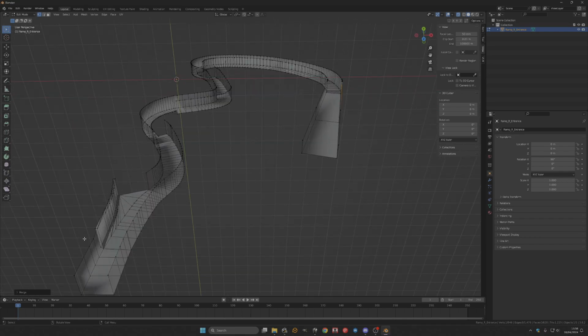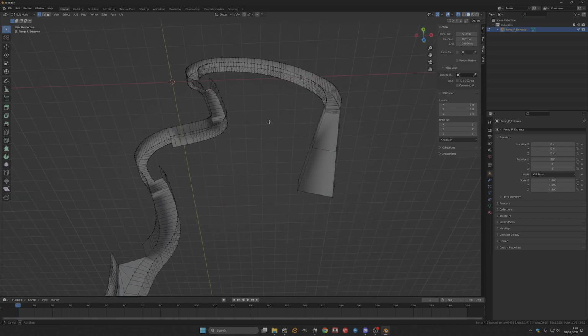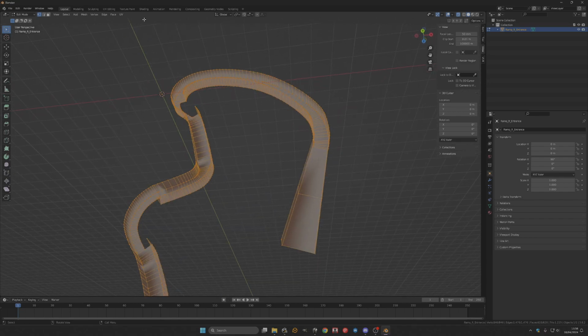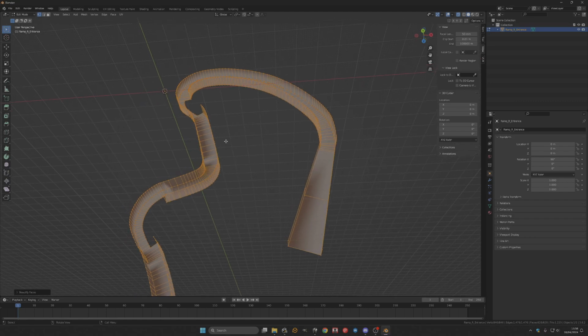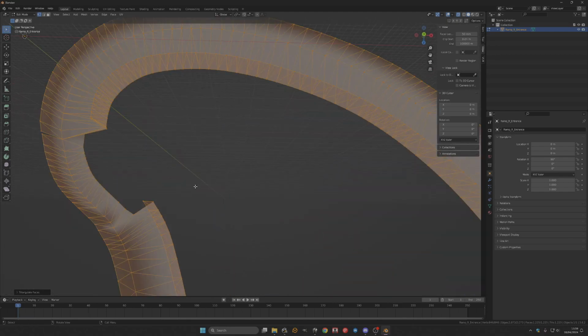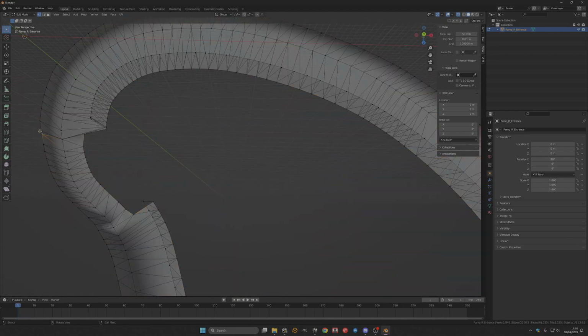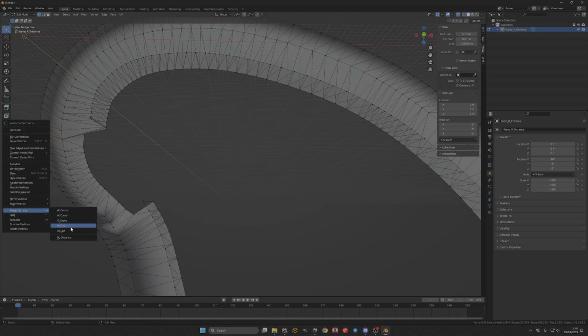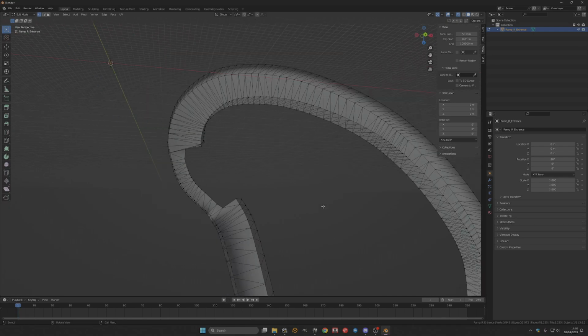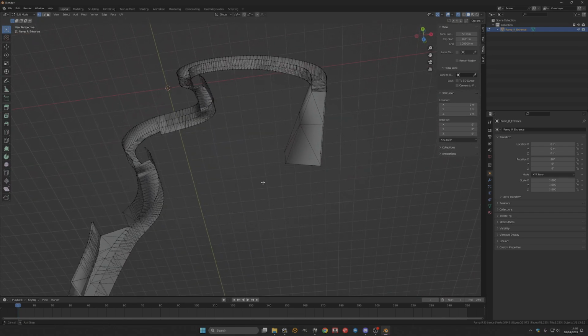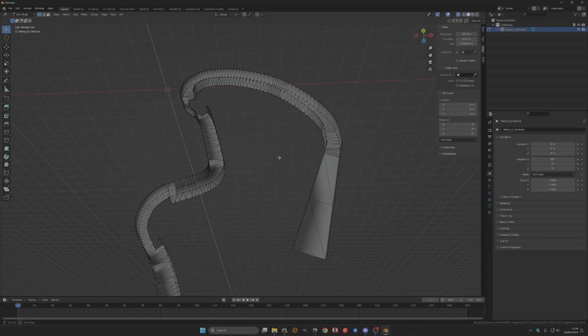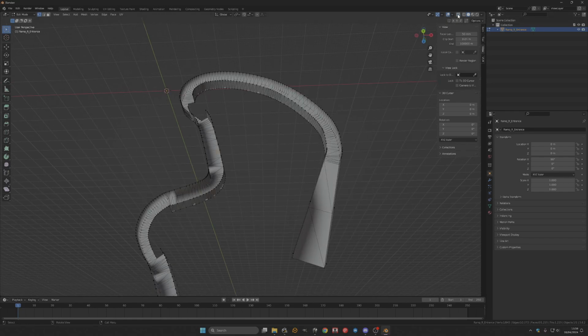I could delete the edge of that because I don't need it, but that's not really important. Select all, face. I think you can usually beautify faces. I'm not the best at Blender, so beautify faces, face, triangulate. Now that triangulating will make triangles out of everything, and there we can see we missed one last. So that's your ramp.